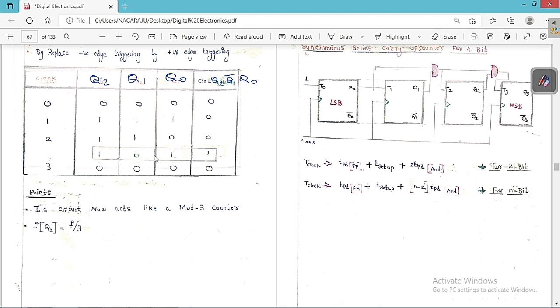So this is called 101, and the clear signal is going to get activated. In the remaining cases the clear signal is not activated. This is the transient state, and then by default all the things are going to become 0, and we are going back to the starting one. So we are going to loop. Only these three are the unique states we are going to get, plus the transient state. So this is called a mod 3 counter.